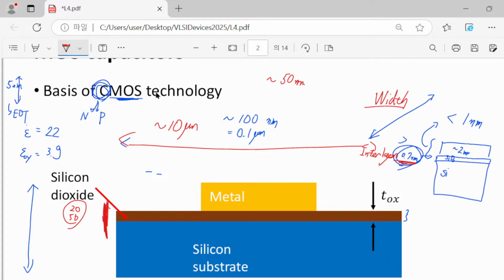So it is critically important to make a uniform oxide thickness, and the rule of thumb is always we wanted to have the thinnest oxide layer. If you can make it thin and thin, then we will do it. But unfortunately, it is not possible at that time. So always having this thin oxide is quite important and difficult job.